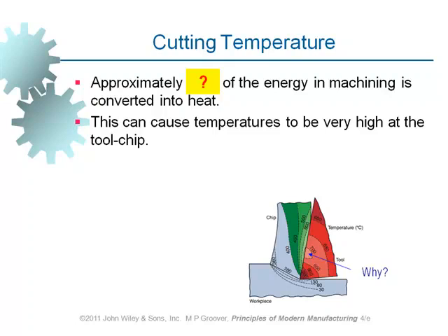The cut is taken, and I've seen many times students touch it with their hand, ignoring the fact that it's really hot, and it burns the skin. That's one of the reasons that you are asked to wear gloves when you are machining the workpiece and doing any activities.